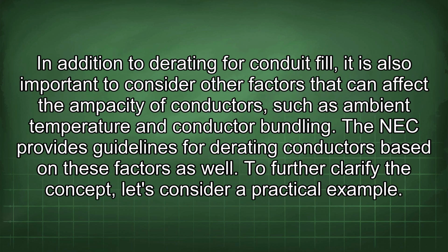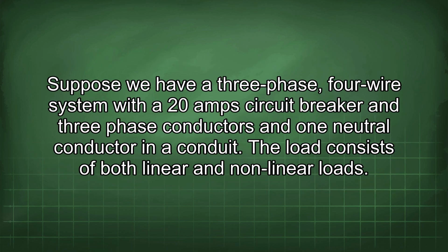overheating. In addition to derating for conduit fill, it is also important to consider other factors that can affect the ampacity of conductors, such as ambient temperature and conductor bundling. The NEC provides guidelines for derating conductors based on these factors as well. To further clarify the concept, let's consider a practical example. Suppose we have a three-phase, four-wire system with a 20 amp circuit breaker and three-phase conductors and one neutral conductor